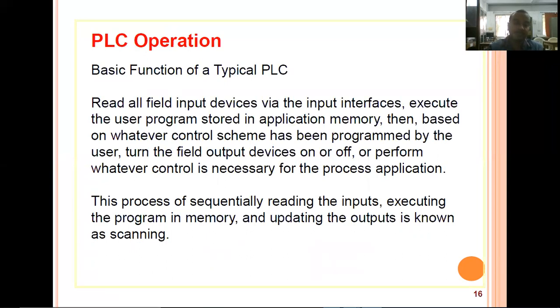So, PLC operation. The basic function of a typical PLC, if we just jot down all the information over here: it reads all the field input devices via the input interfaces, executes the user program stored in the application memory, then, based on whatever control scheme has been programmed by the user, turns the field output devices on or off, or performs whatever control is necessary for the process application.